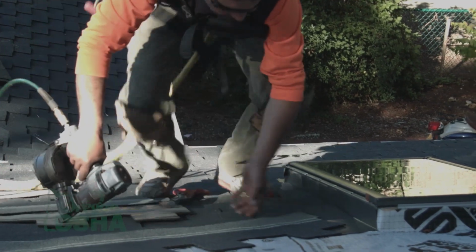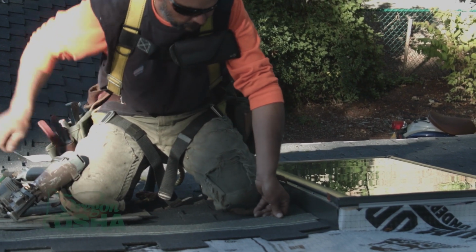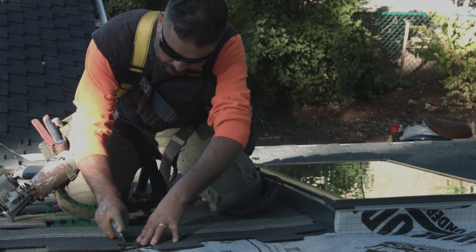But once you walk around it and you're on the other side, you're no longer tied off, because if you fall back through, you're going down through. So you always have to treat it like a leading edge. You can go up to it, but you can't go around it. If you're going to go around it, you have to replace your anchor.